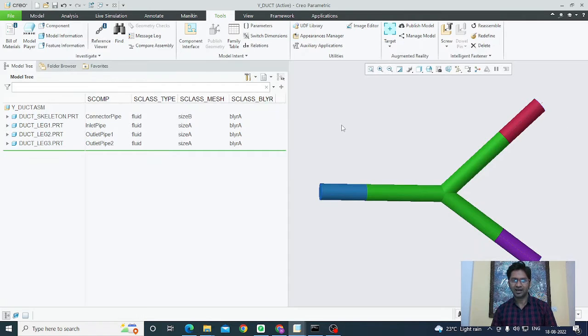You can see here I have opened the Viaduct assembly in Creo, and you can also notice the tagging done here as per the requirement. Here we added a boundary layer value under this parameter named boundary layer against each CAD part. The reason is we want boundary layers to be created for all the parts, and we will be using this 3D class while specifying the boundary layer attribute.